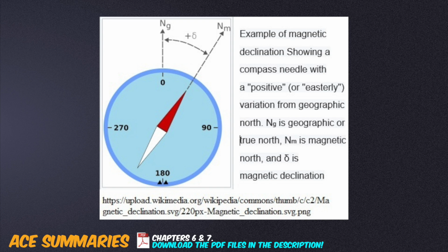If the compass points to the east of true north, variation is east, also known as positive variation. This can be remembered using the following: variation east, magnetic least. Compasses must be reswung, calibrated, when there is a change in the electrical equipment, a large change in latitude, or some other less common incidents such as a magnetic storm.